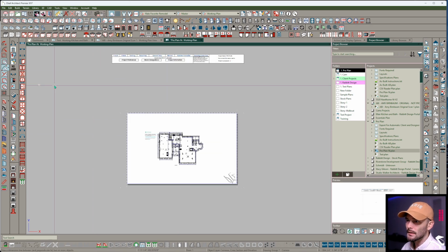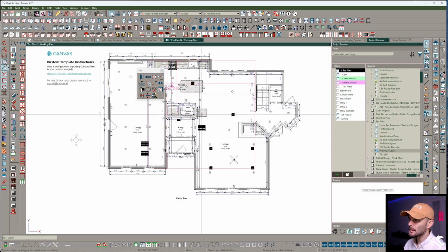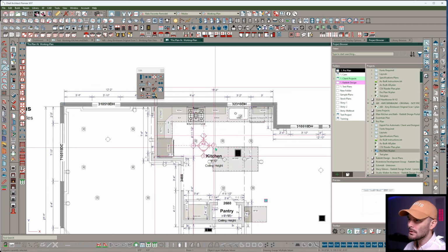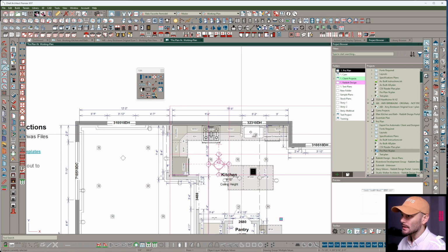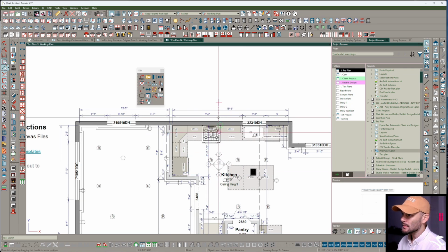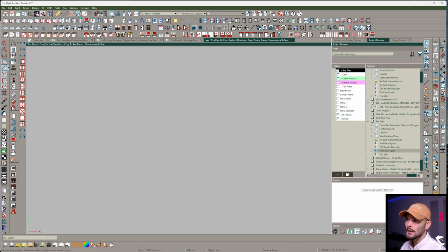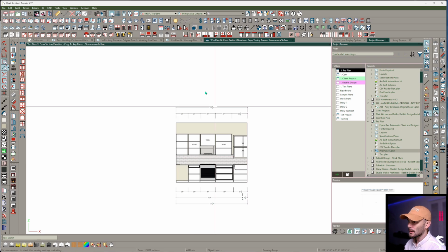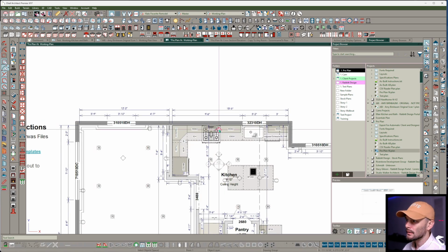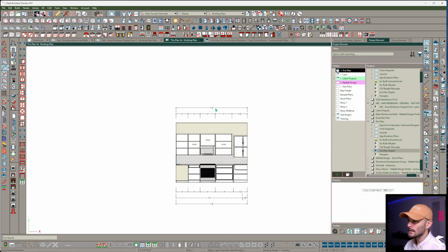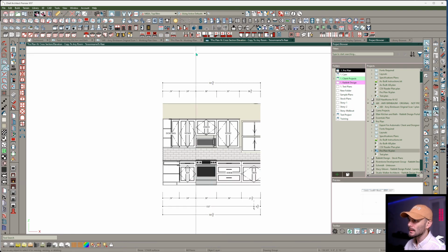And then we've got our elevation camera cluster with the rows. We're going to want to put this into the kitchen space here. There we go. And I can even do something really, really nice, which is, if they wanted to see this, pull this camera inside of the wall cabinet and do a little automatic elevation dimension. And there we go. And then we can pull it back out. And that's going to look like this. Look at that. Very nice.